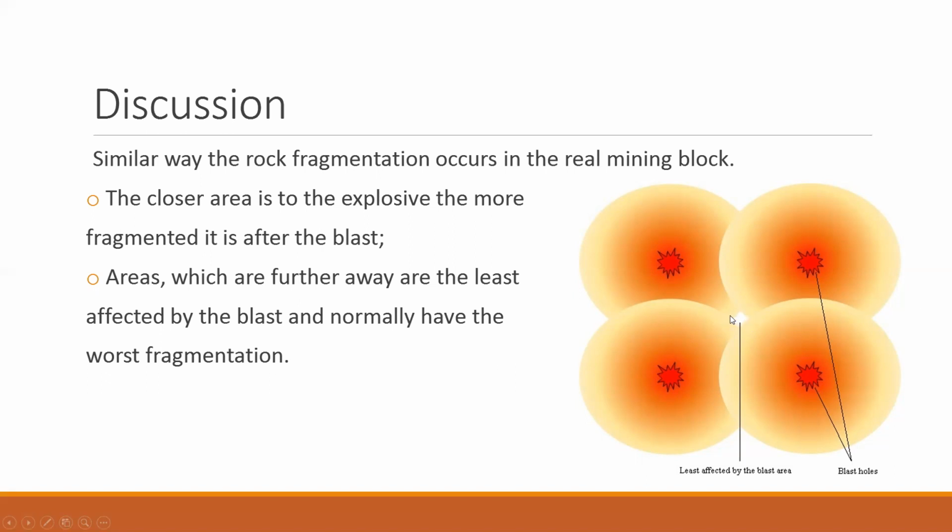So here we have schematically shown a point between all the holes, which is the center of the block in this case, and this area is the least affected by the blast, and obviously it would have the worst fragmentation.